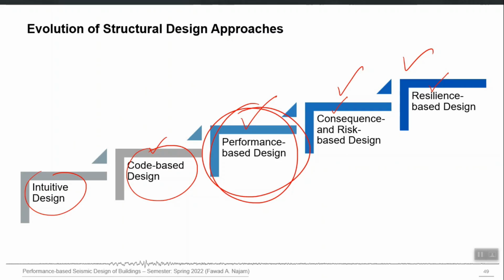There is a classification of seismic design procedures based on this idea also: force based design and displacement based design. Now what you conventionally do in code based design is force based design, right? In code based design, you calculate the forces which the future earthquake is going to apply to your structure, and then apply them to your computer model, and then design the cross section and steel for that loading.